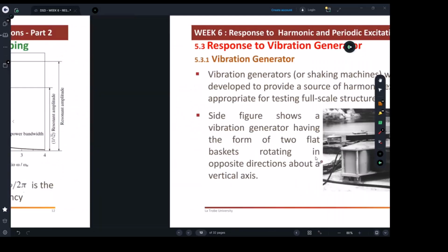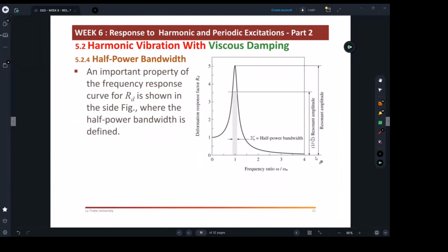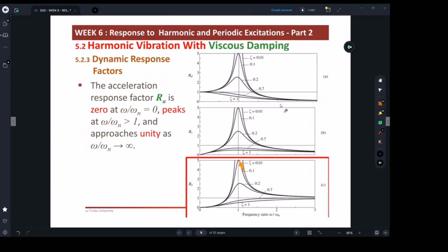Remember, the harmonic motion in theory is not coming from a mass; we're just assuming the force is applied forever. If you remember, whenever the ratio goes to infinity, we either reach 0 for the displacement or velocity case, or we tend to 1 for acceleration.